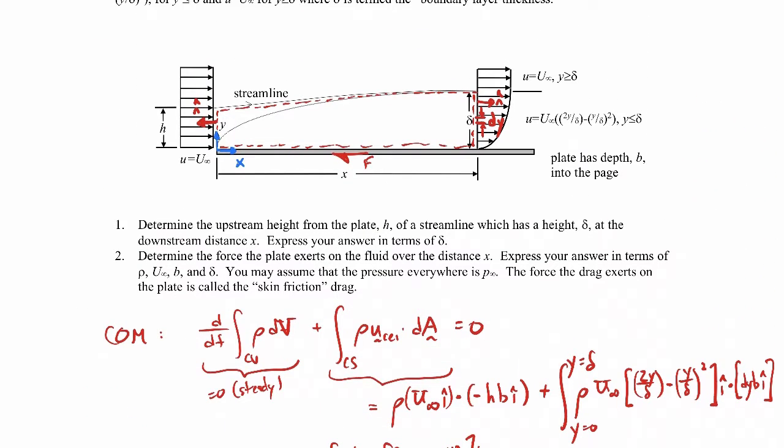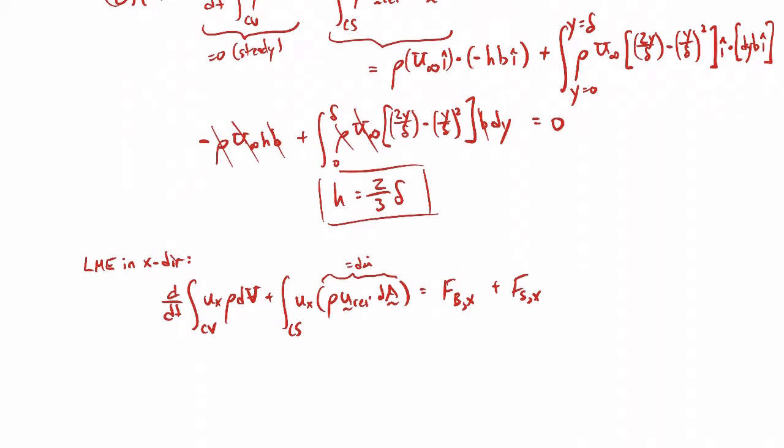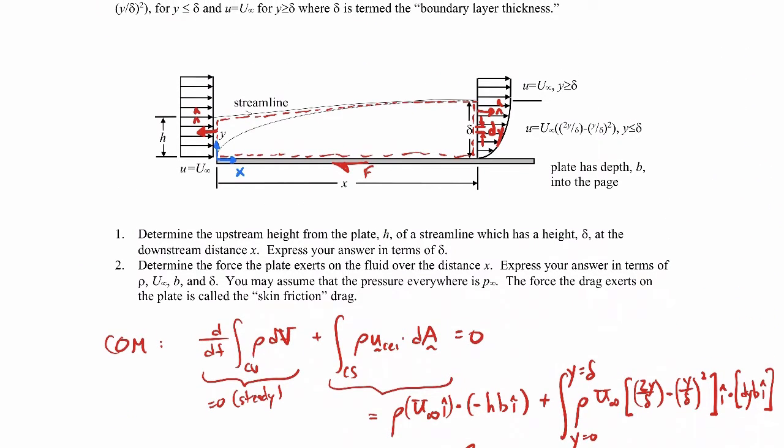So we have our control volume already, and we have our coordinate system. So the first term will be 0 because, again, it's a steady flow. We're saying that nothing's changing with time, so the linear momentum within the control volume is not changing with time. Let me do the force terms next. Body forces in the x direction. We'll say that's 0 because gravity's acting, at best, downward. So we don't have any body forces in the x direction.